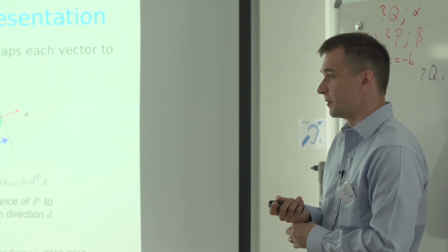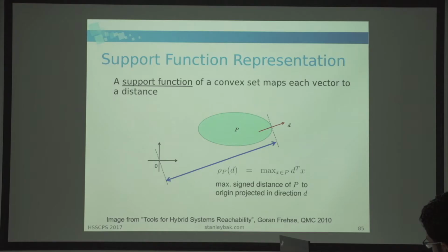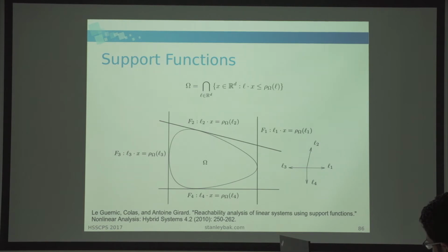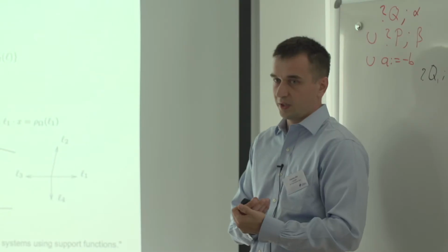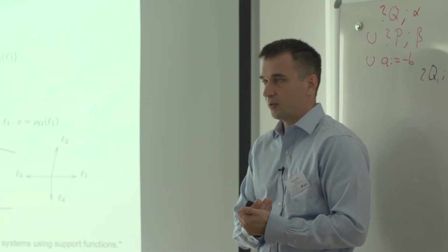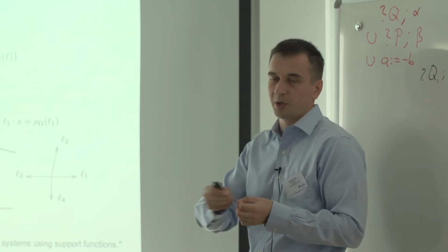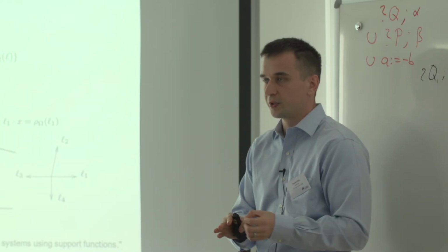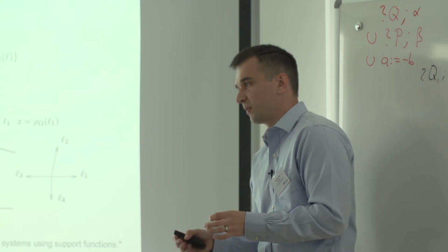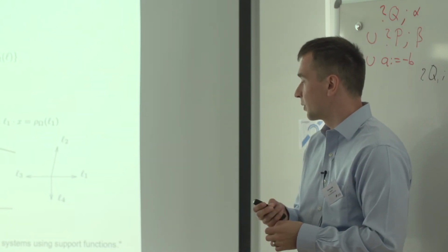So it's a little bit more general than zonotopes, right? It doesn't need to be centrally symmetric. You can do approximations of complex sets using zonotopes. So if I have a very complicated set of states I'm tracking, I can imagine computing the box over-approximation of the set of states. That's just, you take a support function and you evaluate it for particular directions. So the real support function might be this very complicated thing, but I can sample it in certain directions very quickly.